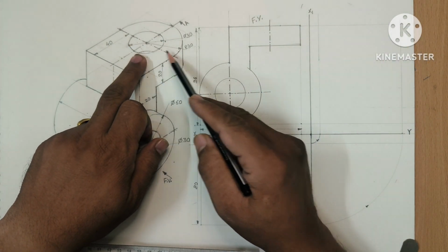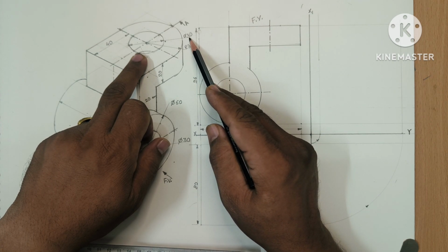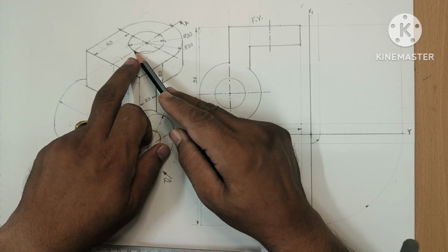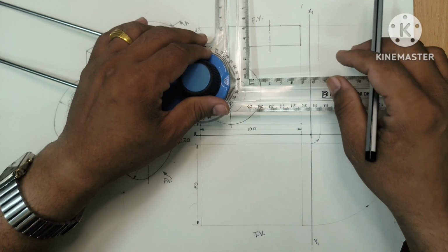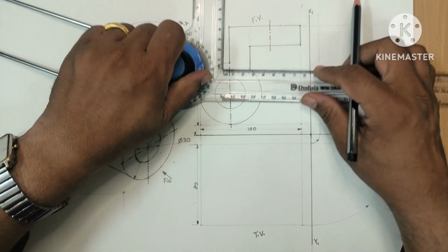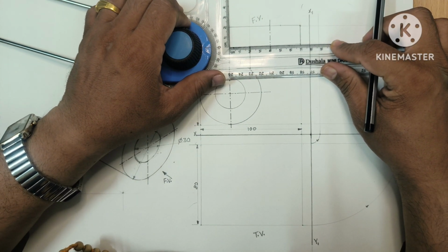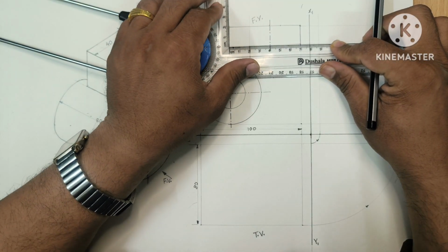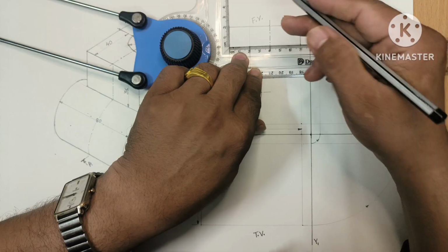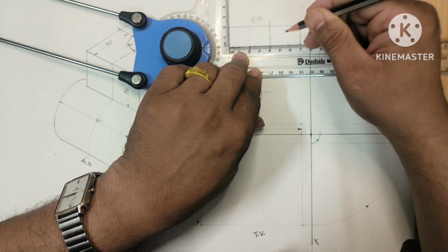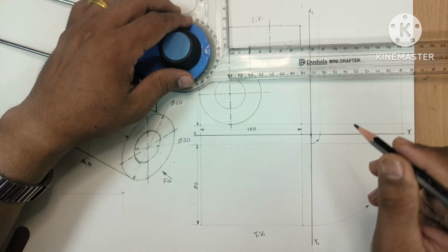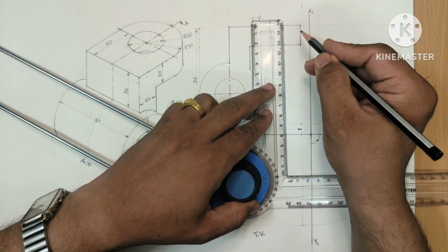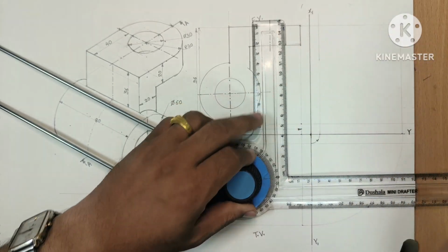And the middle circle is having phi is equal to 30, means diameter is 30, means from this point 15 millimeter distance towards right and 15 millimeter distance towards left, means that will be 30. Hence I will draw the continuous line, because we have taken the sectional view.